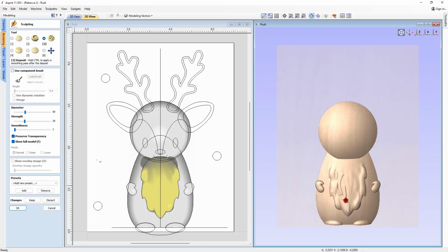So we can go in and create these effects. All I'm doing is drawing in a series of lines, and you can see even when I come out, it's not doing anything because we're only sculpting the actual fur part. Okay, now if I go into the smudge tool, if we just increase that diameter, maybe just a little bit, and then using the left arrow key, the down arrow key, I'm just going to decrease the strength. And then I'm just going to go back and forth, okay?